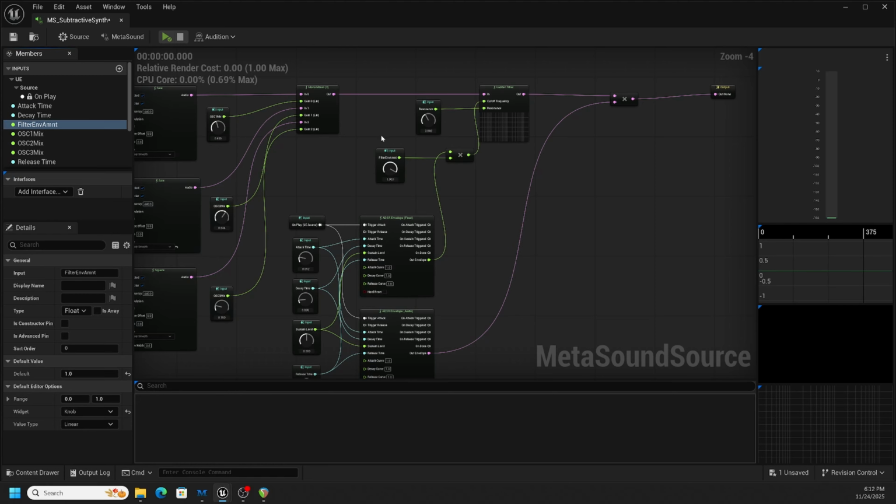Okay, so the range, certainly 0 to 1 is not going to work here. I kind of like with this to be ideally like 200 to be our lowest frequency. It would go down to maybe 100. But the top needs to be, theoretically, 20 kilohertz. But for our purposes, putting it at 10,000, like I mentioned earlier, is not too bad.